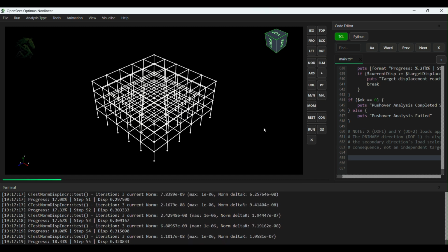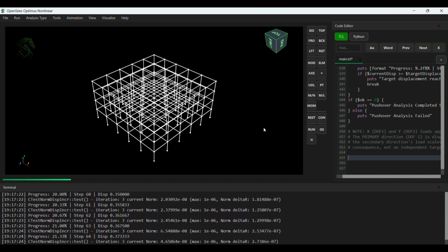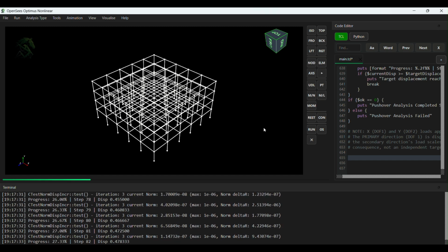Working order in summary: set base shear and pattern type for each direction, choose which one is primary, fill in both load tables, review the merge pattern, then run.